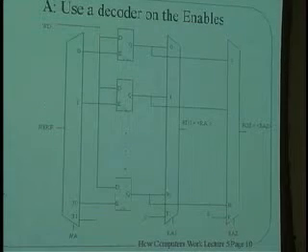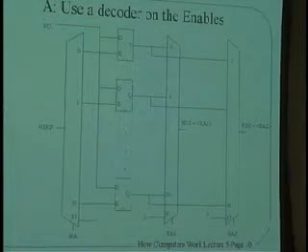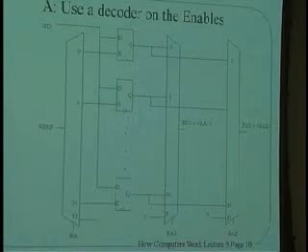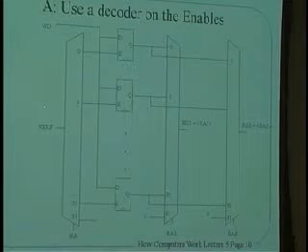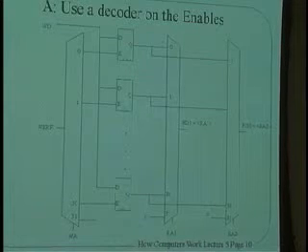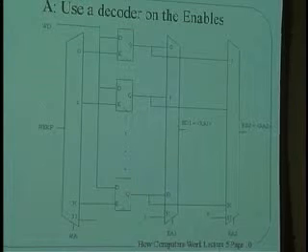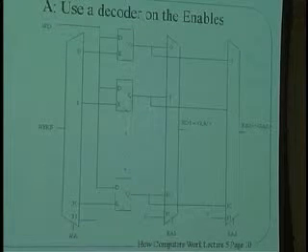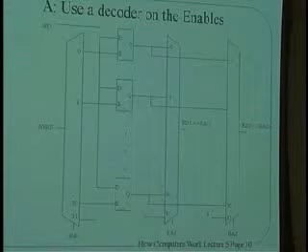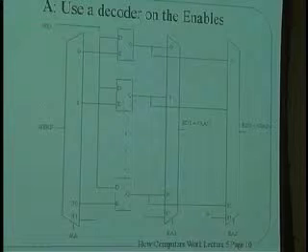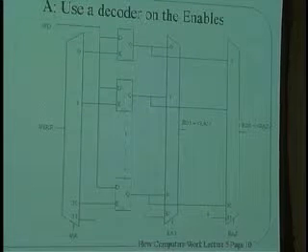You said the WRF is only 1 bit, 1 or 0, right? That's correct. But why would it ever be 0? Because then that would mean that even the address it specified won't be enabled. That's absolutely right. But we did see some instructions in the, not the last class, but the one before, for instance, a store instruction or a load instruction where we did not want to write the register file.